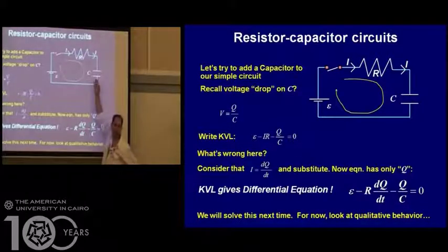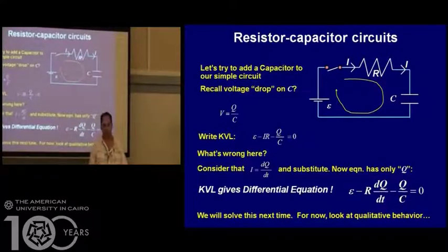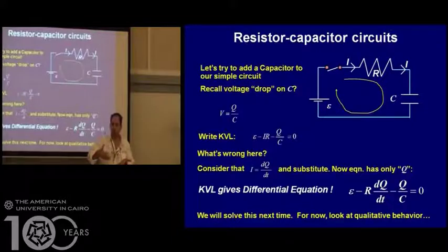What's an equipotential surface? Someone said a wire in here. Yes, wire. So at the beginning, at time equal to 0, once you switch the switch on, this will act like a wire. The circuit will be like just the battery and the resistor. Then what happens after that? Charge will start to accumulate on the two plates. This will be fully charged. It will be fully charged in such a way that the potential across it equals the potential across the battery, and no current will flow.